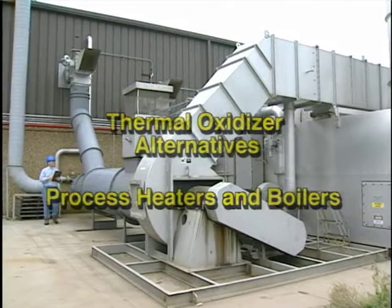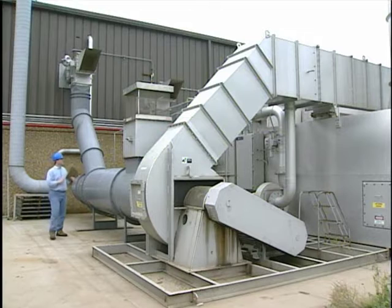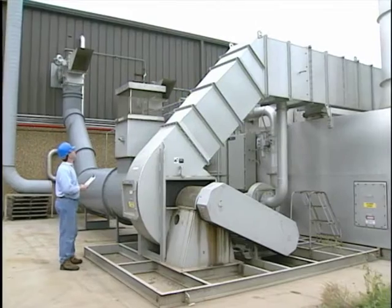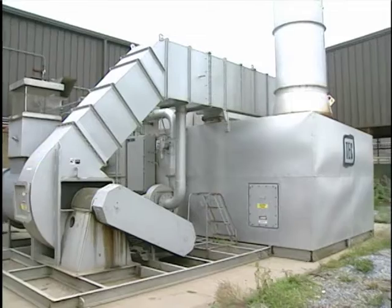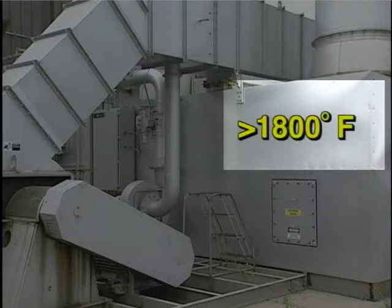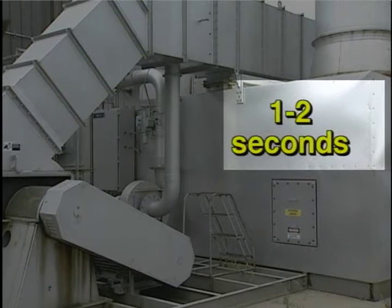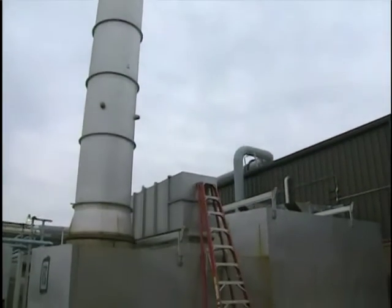An alternative to installing a thermal oxidizer is to incinerate the contaminated gas stream in a process heater or boiler. This avoids the capital cost of new equipment. The contaminated gas stream is typically injected close to the main burners or may be used as part of the combustion air supplied to the burners. Process heaters and boilers are normally designed to operate with combustion chamber temperatures greater than 1,800 degrees Fahrenheit and with flue gas residence times in excess of 1 to 2 seconds. These conditions are similar to those of conventional thermal oxidizers.